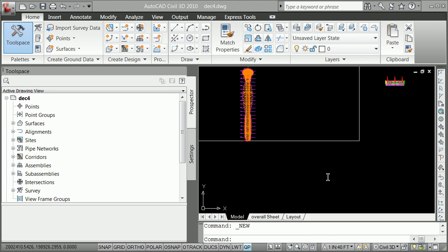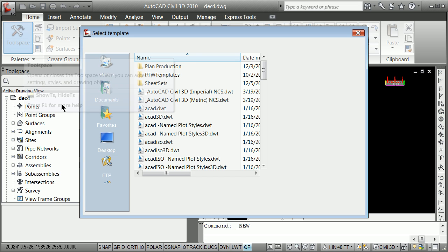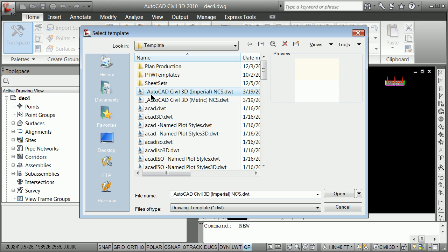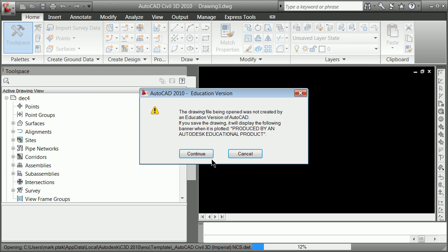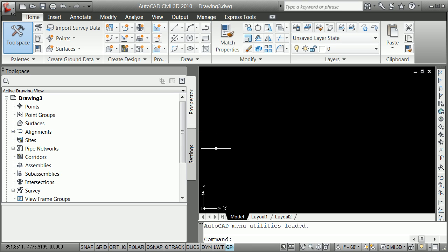Okay, now that I've got you all convinced that you can only use the DOT template, we're going to do a pipe work here, and we're going to do that by beginning in a more standard template that you all know how to use by doing File, New. Remember that? AutoCAD Civil 3D Imperial. We do this mostly because I don't think the DOT completely has all their storm stuff together, but it's my expectation that if they don't have it together already, they're going to have it together soon.